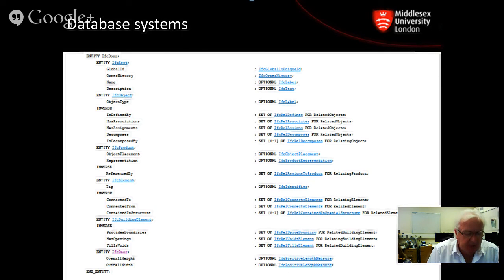So the reason I'm doing some of this today is I want people to understand IFCs better than they are understood at the moment, because there's a lot of misinformation and misuse of information out there about IFCs and what the current capability of the IFC model is. Mark Bew, for example, the leader of the BIM task group, will say it's the best we've got, and it is. But it still needs an awful lot of understanding and explanation to get complete data movement amongst the software platforms that we actually use.